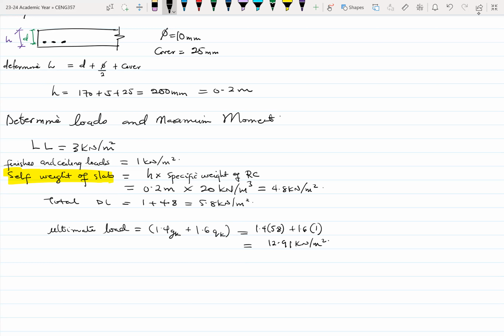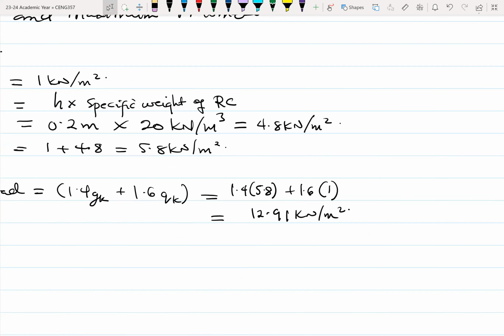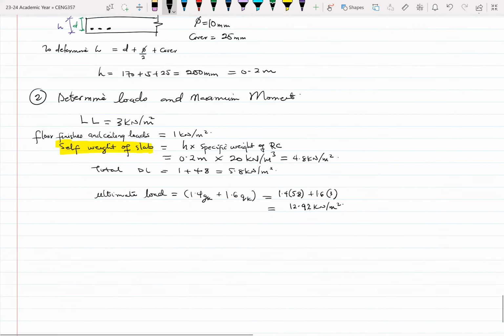Let me see, 5.8 times 1.4, which is 8, plus 1.6, 29. I'm making a mistake. Oh, sorry, 1.6 times 3, not 1. The live load is 3. Okay, so maybe that's how come I got a different answer. Okay, so I get 12.92. All right, great. So I think I'm on the right path.